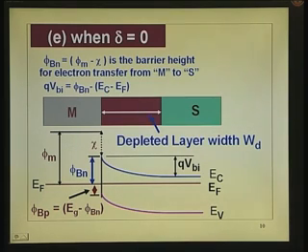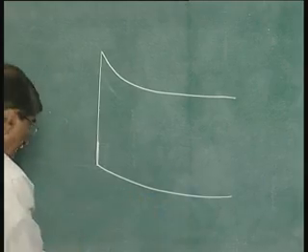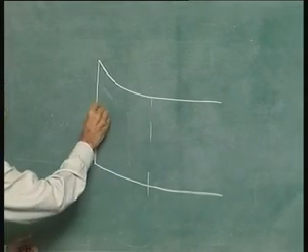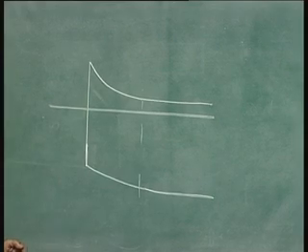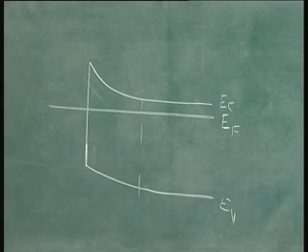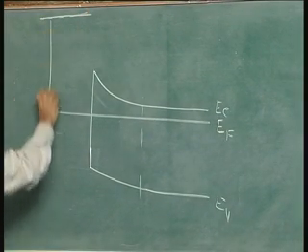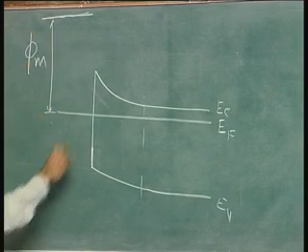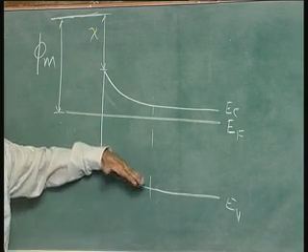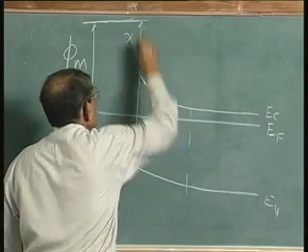So, what we are trying to see is you have the contact like this. I am redrawing that diagram. The conduction band, valence band, etc. This is where up to where the depletion layer is present. Then I am putting this Fermi level here in contact, aligned with respect to each other, just like the case of p-n junction, EC, EV. Now, what we are showing there is the vacuum level, that is the vacuum level, and this is phi m. I am redrawing it here for clarity, and this is actually equal to chi. Wherever potential changes take place except Fermi level, all other energy levels follow the same path. So, this level also will go from here, we will go like that.